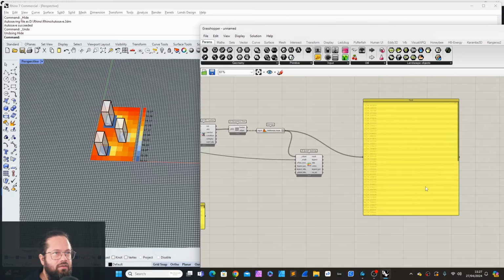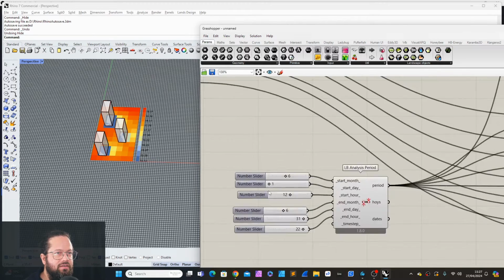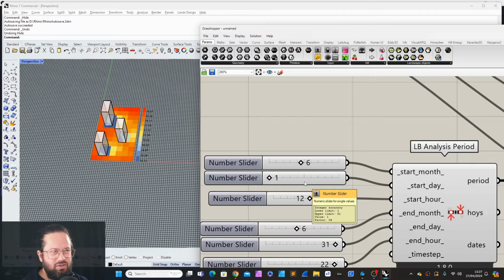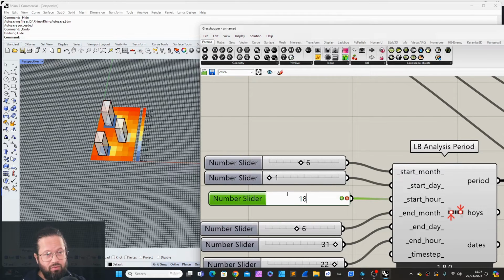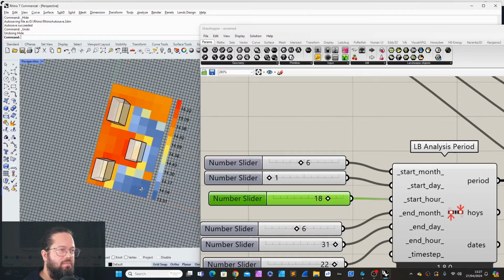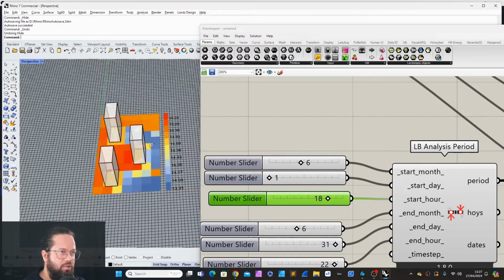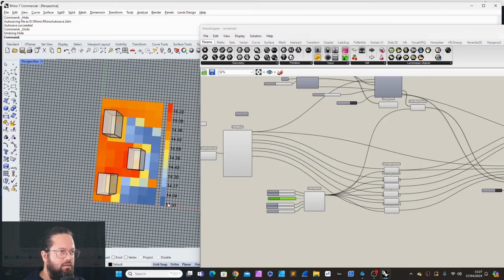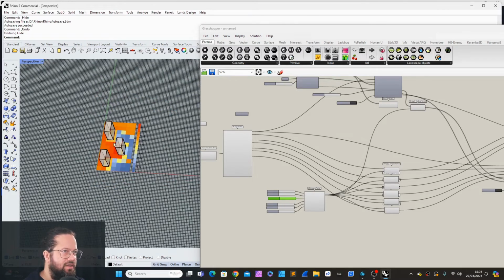It's the average. Now we could of course play with this and say, oh okay, let's check what's the perceived temperature, which is the UTCI. What is that in the evening? So we could just slide this here to, let's say, 6 p.m. So from 6 p.m. to 10 in the evening. Okay, that has quite a change. It's quite a change, most likely because of the shadows of the building. It's slightly cooler in the shade. So you have the evening sun coming from that side.